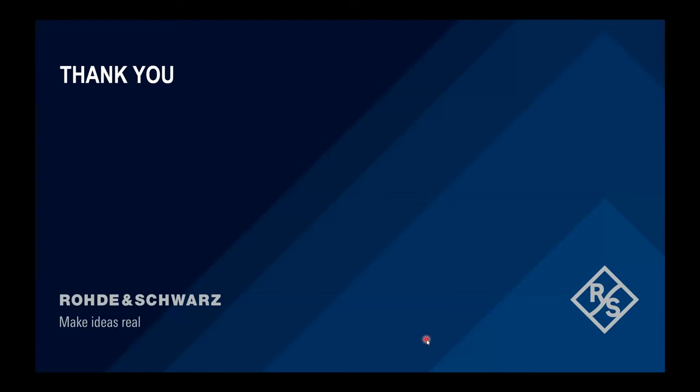This would give you a bad statistic on your device. But if you have deskewed everything properly and your device is statistically behaving nicely, then you see immediately the correct losses. Typically, I would recommend to first of all do the deskew and afterwards let the measurement run over a certain amount of time to see if maybe also heating changes the behavior and the losses due to parasitic effects like thermal coefficients and so forth.